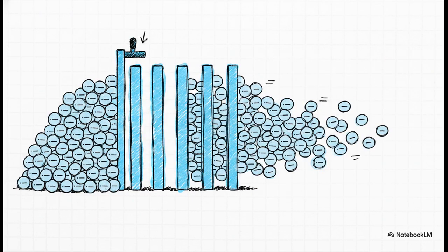Eventually, an incredible microscopic standoff occurs. Once this rapid tug-of-war reaches an equilibrium, a state where the outward diffusion current perfectly balances the opposing inward drift current, the border finally stabilizes. We now have a completely stable PN junction.